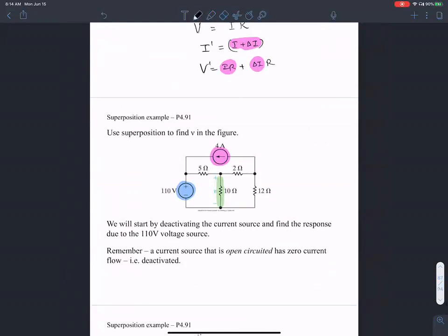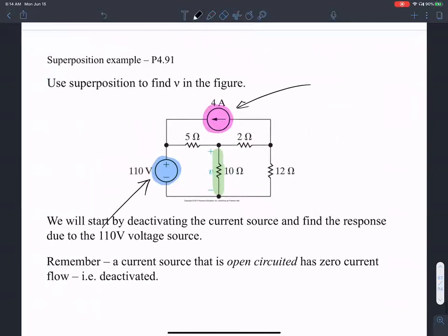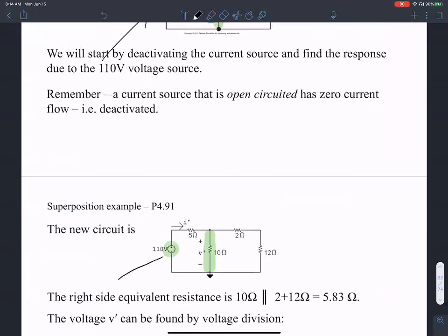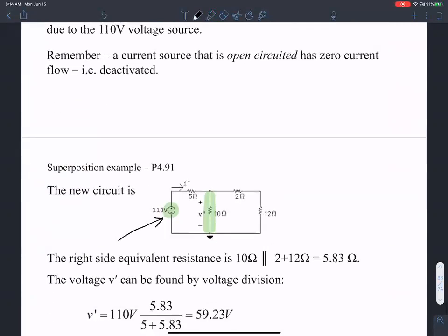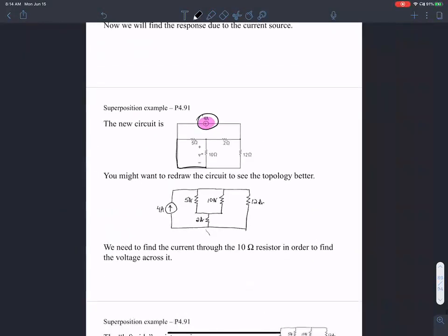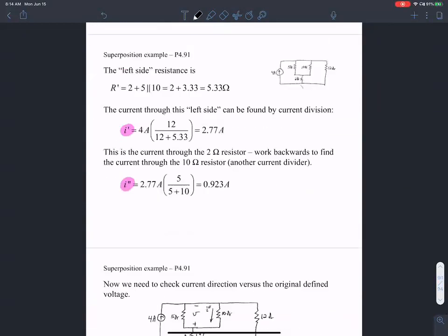When there are two sources, in a linear system, I can find the effect of one source by deactivating the other, then do the exact same thing with the other source by deactivating the first one, then add the two responses. Then I'll get the combined effect.